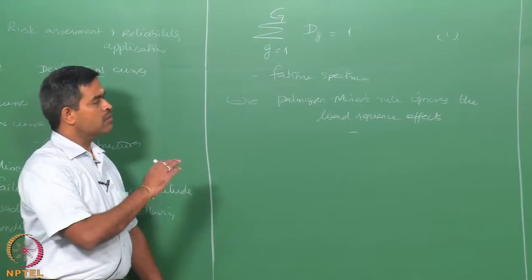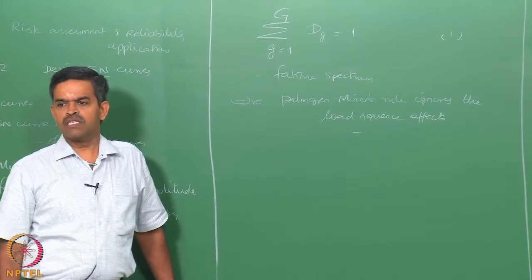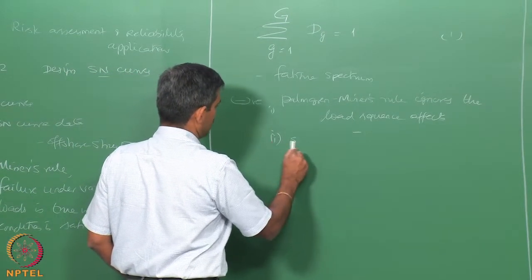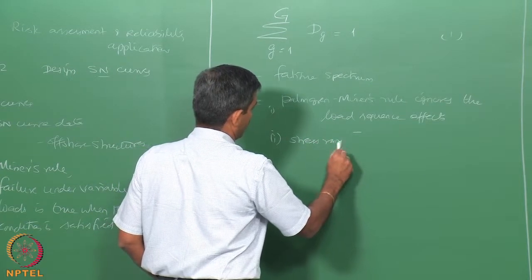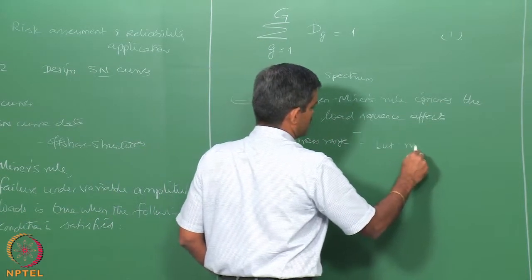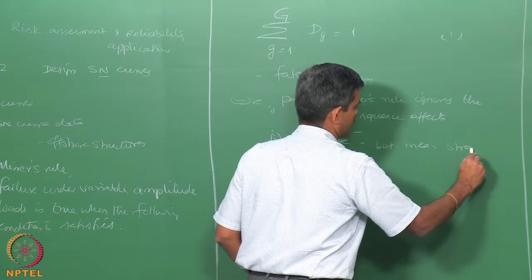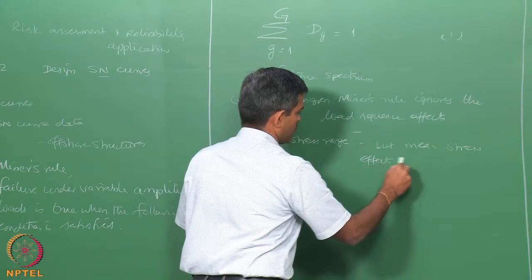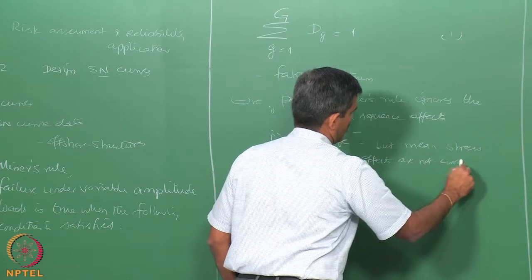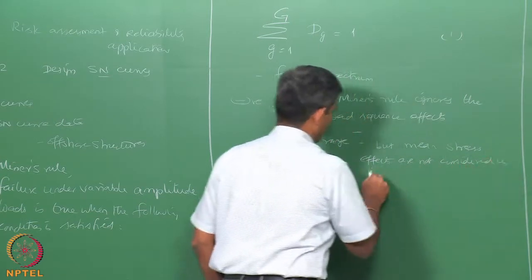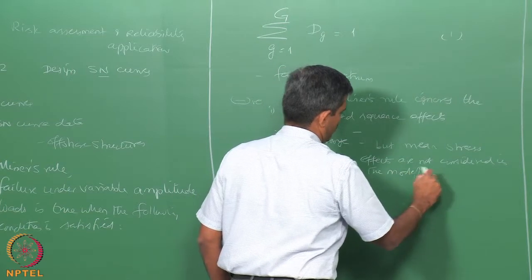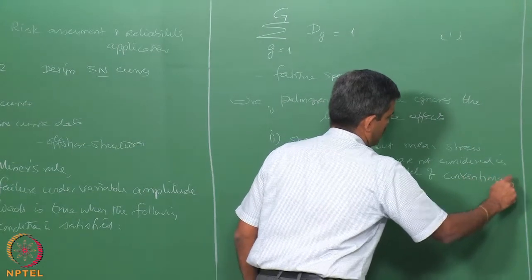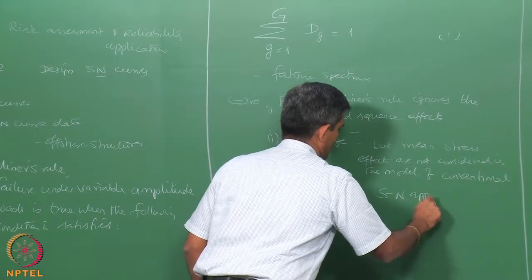Further, when the study or discussion applies to offshore structures, the mean stress effects are generally not considered. So, we are talking about the stress range, but the mean stress effects are not considered in the model of the conventional SN approach.